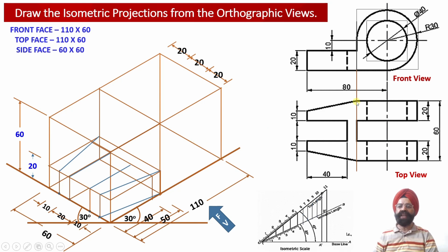So before we start with construction of these four vertical circular surfaces, let us proceed to evaluate four square projections in this isometric projection construction. This is the first face, that is the rear face of the solid, which is a square. Now at a distance of 20 millimeter, we are going to obtain another square projection.